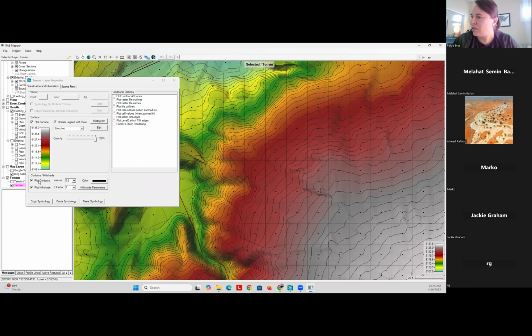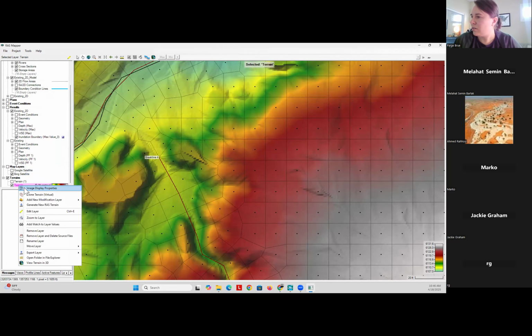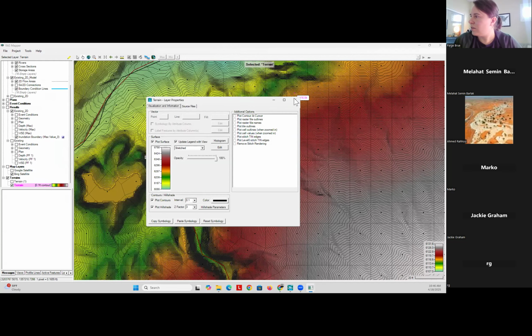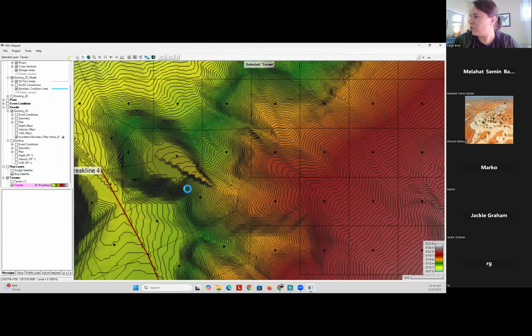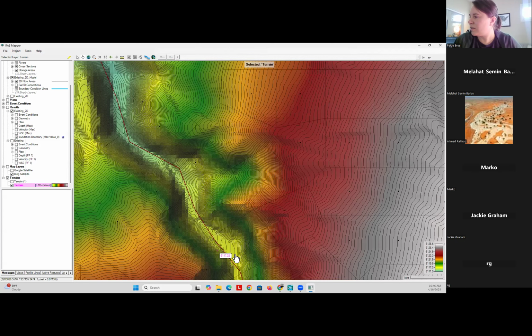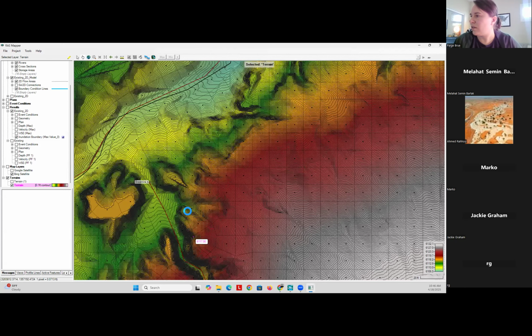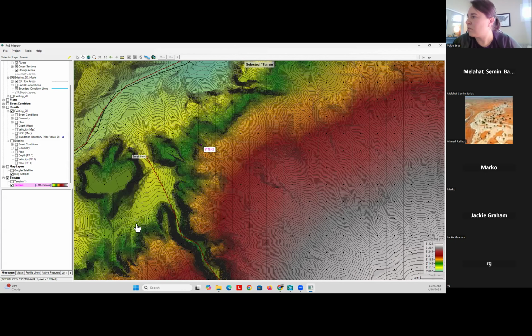Another thing that's really helpful, like I said earlier, is adjusting these contours. So if you're drawing break lines and you want to get them in just the right spot, you can turn on really high resolution and make sure you're following the contours. Maybe I'll fix this, and then it would follow these contours perfectly and make sure flow is aligned. The cell faces are aligned with flow.